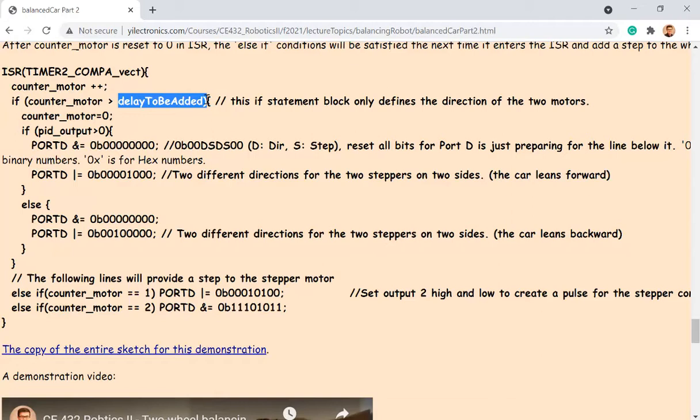Okay, look at my hands. That's the overall number over here, right? I have a counter, it's counting from here to here. I can only trigger a step when the counter moves to 1. And then I clear myself. Then it starts counting to here, and then comes back to clear itself, equals 0. So that's how you clear itself, and then you get another chance to count to 1, then you can trigger another step. If you have a longer time here, it takes a lot of time until it comes back to 0 again. If you have a smaller time period, then it's from 0 to 1, done, come back to 0, 1, done. So whenever it comes to 1, it triggers a step.